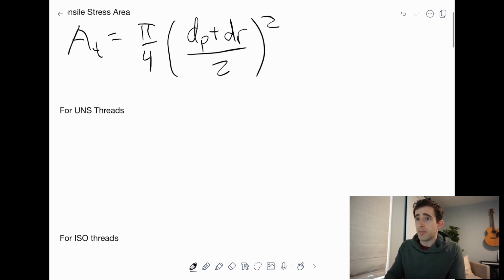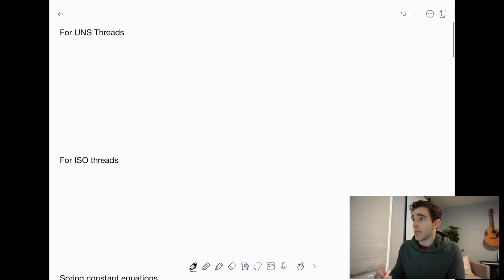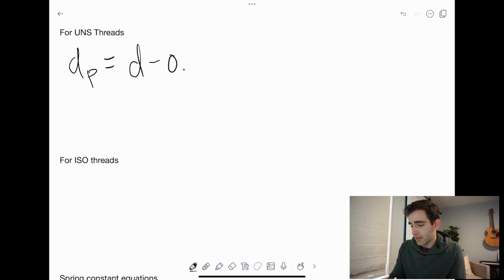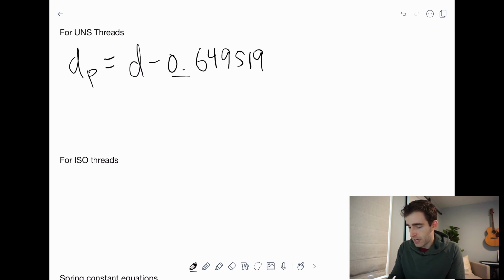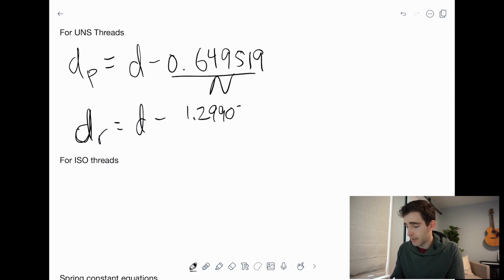In this case, dP is going to be the pitch diameter, and for UNS threads, that is D, the major diameter of the screw, minus this constant divided by N, or the threads per inch. And dr is very similar, a specific constant divided by the threads per inch.